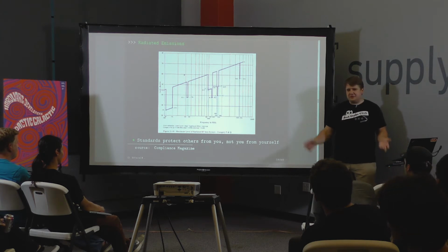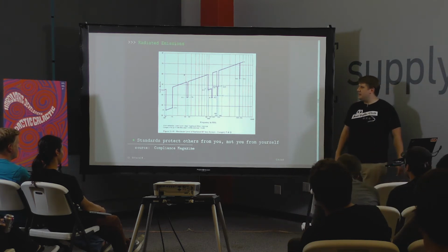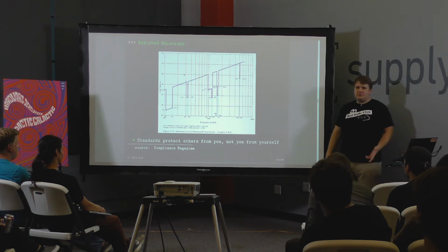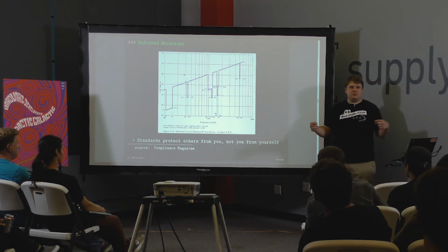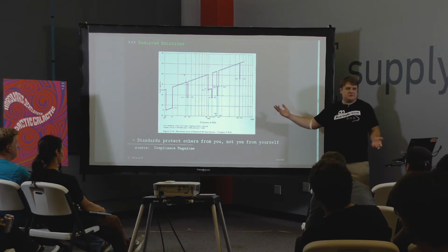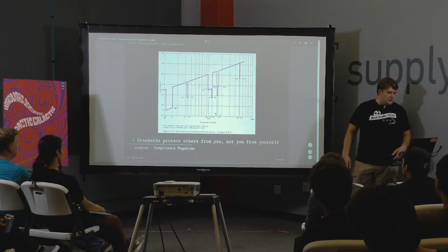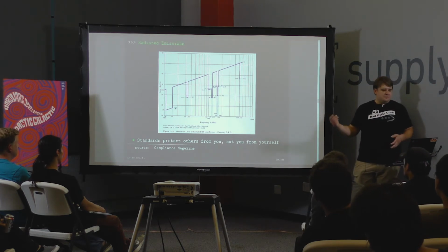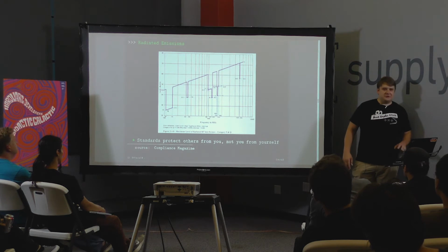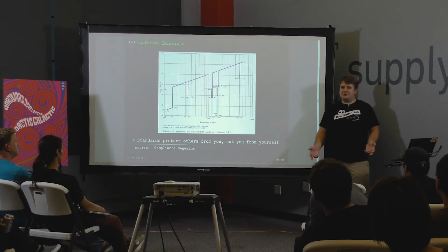Even if you're sending something to the stratosphere, you want to be mindful of EMI and EMC. But the problem is a lot of the standards that are available are designed to protect other people from you. This is DO-160, which is the avionics EMC standard. This is the mask that you want to keep underneath, in dBV per inch. And this is where your terrestrial radio stations are. They just want you not to interfere with FM broadcasts on Earth.